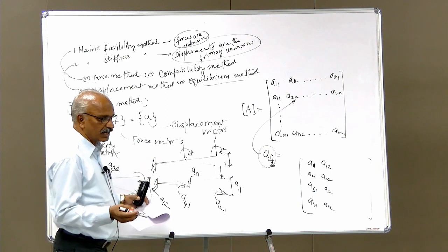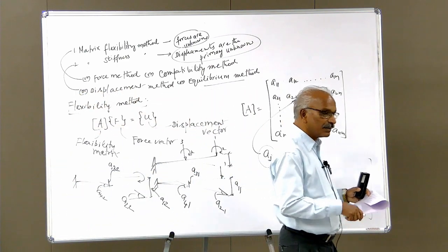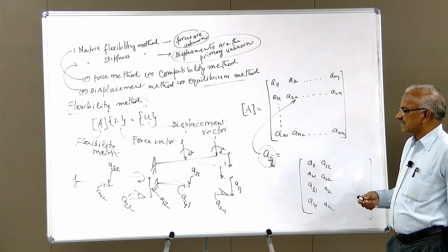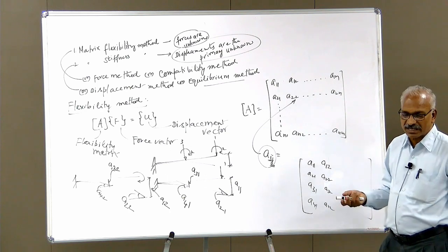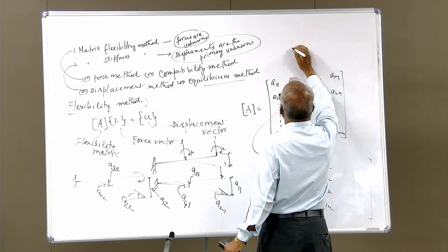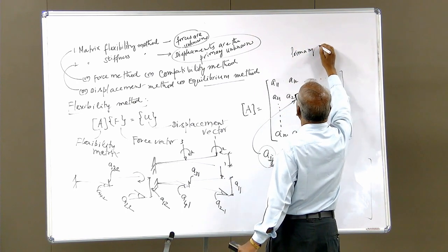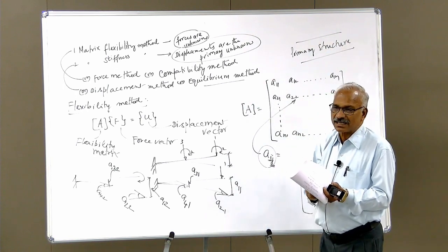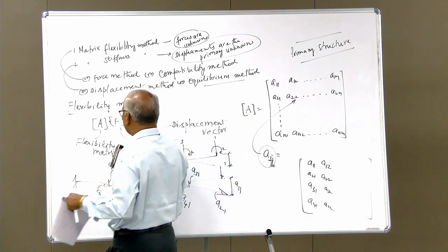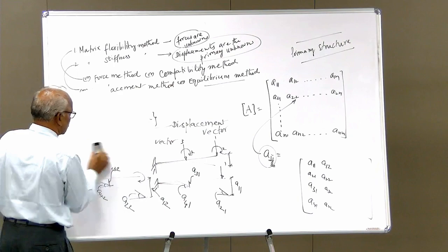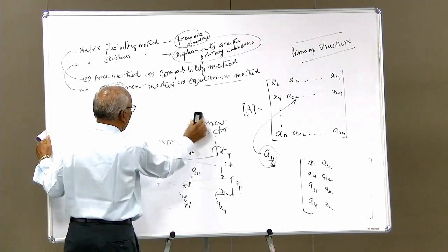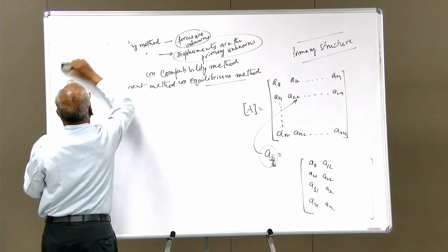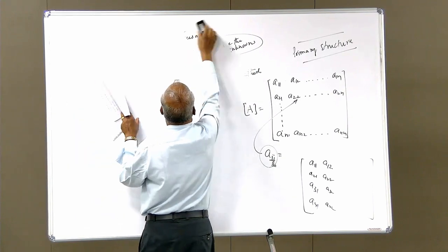Then what are coordinates? Coordinates, as we discussed, are points and directions in which a measurement is desired. And then as far as the matrix flexibility method is concerned, when you analyze a statically indeterminate structure, you have another term called primary structure. Now primary structure is a statically determinate structure. So whatever may be the structure, the first step is to find out the degree of static indeterminacy and identify the determinate structure by removing as many forces as required for making the structure statically determinate.